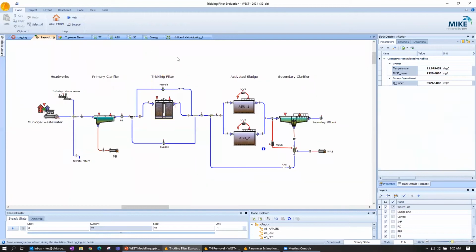So that tells us that maybe there's some spare capacity in this activated sludge system, because whether or not we took out the COD in the trickling filter, the activated sludge tank seems like it didn't notice. So that's kind of the final bit of calibration. Calibrate our understanding, but also calibrate the individual models within the plant.